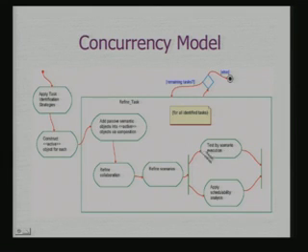Once you have the scenarios, you test each of the tasks by scenario execution and apply the schedulability analysis. That is, whether the tasks can be scheduled. If it is schedulable, then what are the constraints the task should satisfy, in fact, what kind of execution times the task should meet. That will again dictate your choice of the processors.